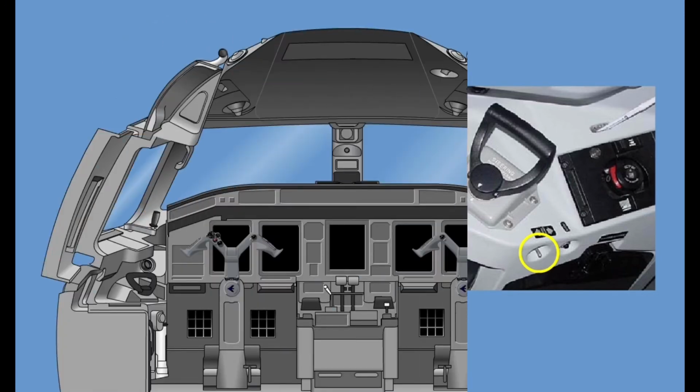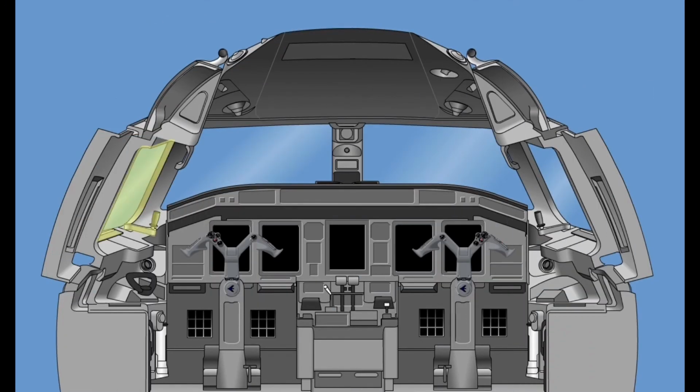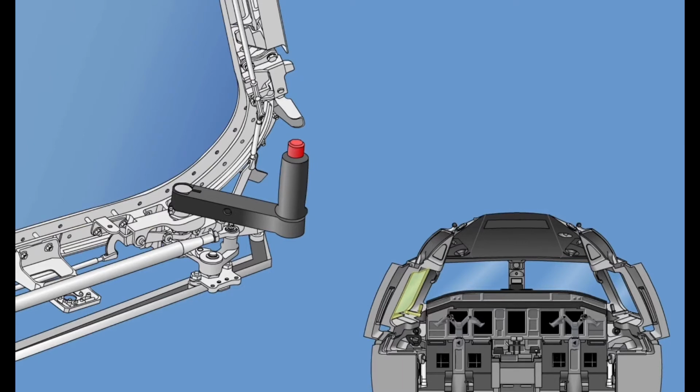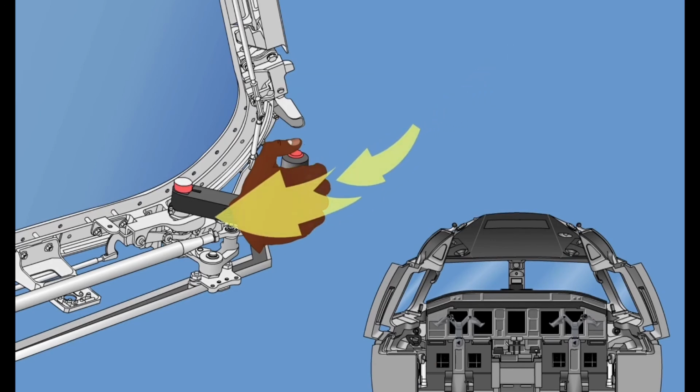The crew emergency windows are located in the cockpit on the left and right-hand sides. When closed, they are pushed against the window frame by an over-center mechanism and held in position by a locking mechanism. The windows are opened manually. They have a locking mechanism that is released by pressing the button located on the top of the handle. As the window is unlocked, the handle must be pulled backward in order to actuate the roller's latching mechanism, sliding the window inside and backward along the tracks.